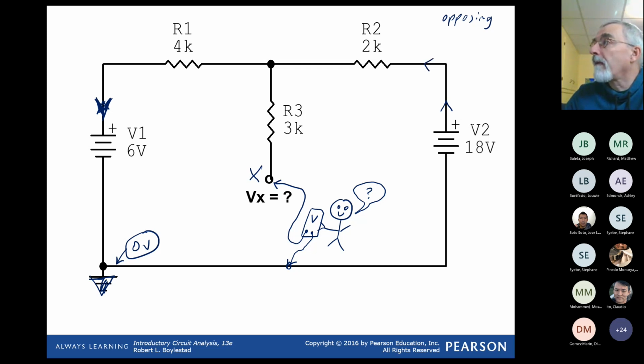And let's trace current flowing through here. If we go with opposing and the larger one wins, and that we don't have something really tricky like next chapter, what will happen is current will flow from the larger battery, cause a volt drop across this resistor. The current encounters a node or junction, and here the current has to decide how much will flow this way and how much will flow this way. We could use current divider, and it will follow the current divider principles.